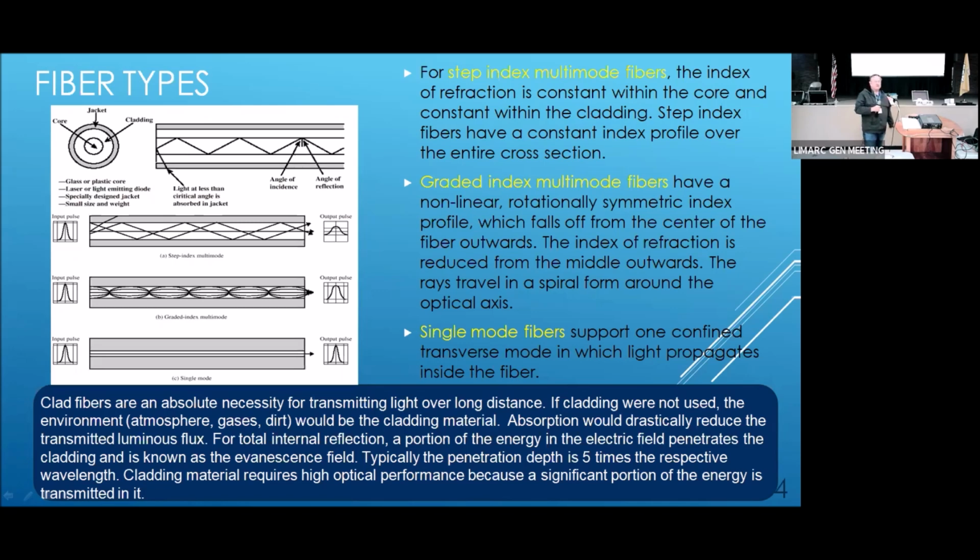The carriers, they don't want to go 1 or 2 kilometers. They want to go a really long distance. All right. So we have what we call single mode fiber that has an extremely thin core and a very well-defined cladding there. It only supports one path through that fiber. That's why it's called single mode. Each path through the fiber is called a mode.